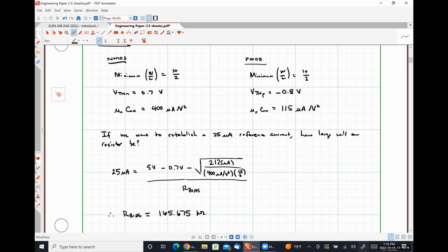You have a system in which your supply voltage constantly decreases as you utilize the device, which means you're constantly changing your reference current, which means all of your transistors behave worse and worse as your phone call goes on, or as you Google more stuff, or text people, or look up cat videos on the internet. Resistive biasing is garbage for performance ICs.